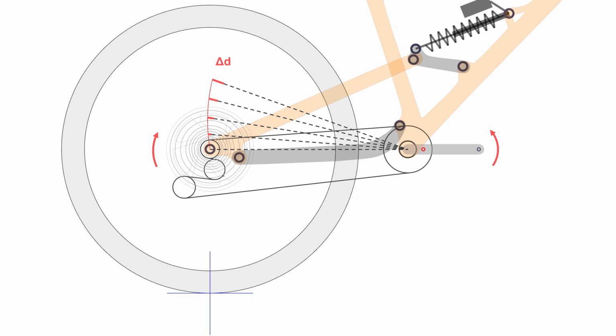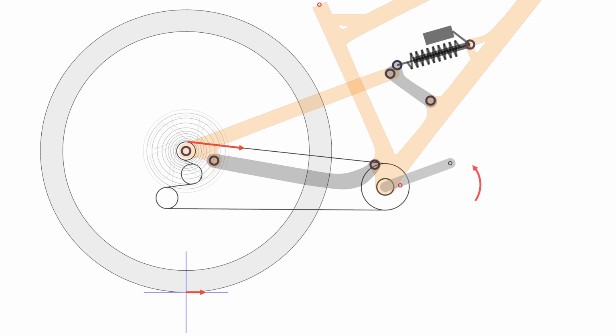When the suspension compresses while riding, the chain will always try to rotate the cranks backward. But with the rider's weight on the pedals, this rotation is resisted. So the only remaining option is to rotate the cassette. But if the freehub is engaged, then the entire wheel must rotate with the cassette as well. This rotation may again be resisted by either braking forces or the inertia of the bike rider system stopping the acceleration. That means both rotation paths are blocked, but something still has to move. What happens is that the chain ends up turning the cranks and driving the wheel forward at the same time.